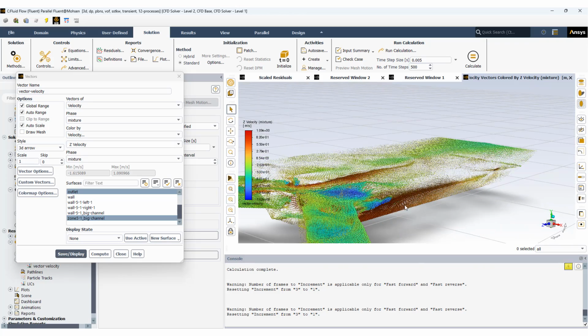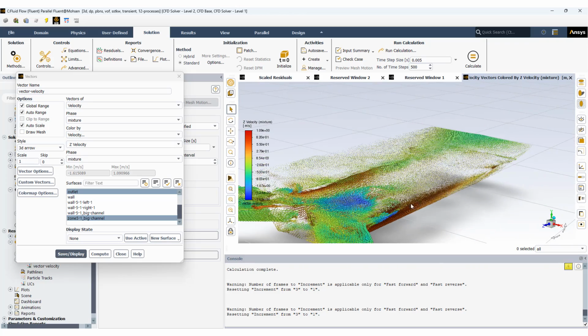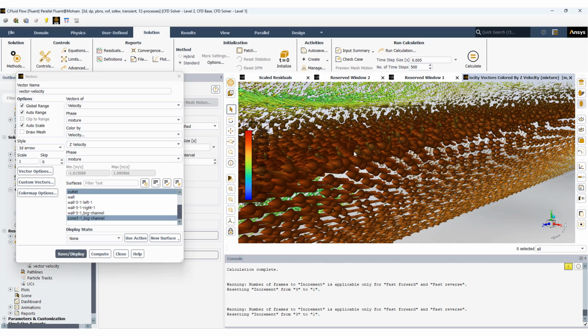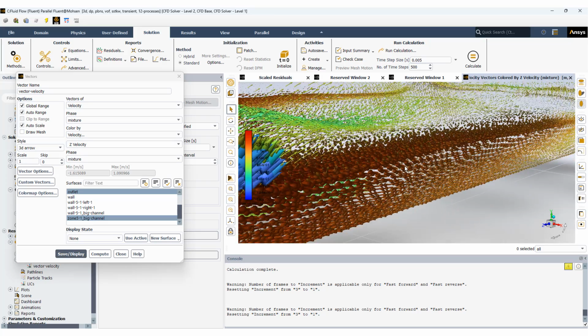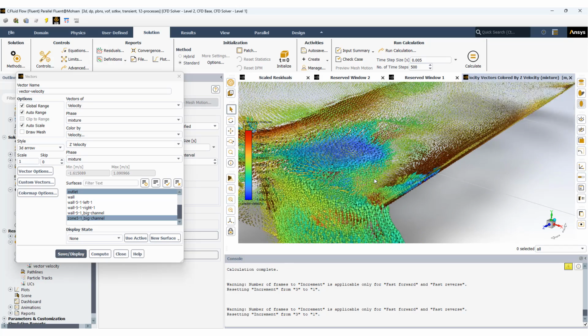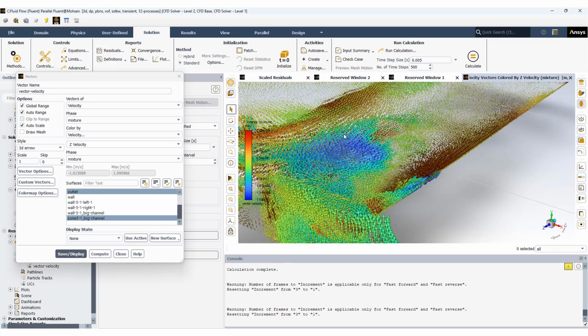At the sides, where we saw in the animations that the waves travel backward, you can see this by the positive values. The arrowheads point toward the positive velocity for the z component, and here these are negative, so it means that after the merging these two flows push the flow going toward the outlet.